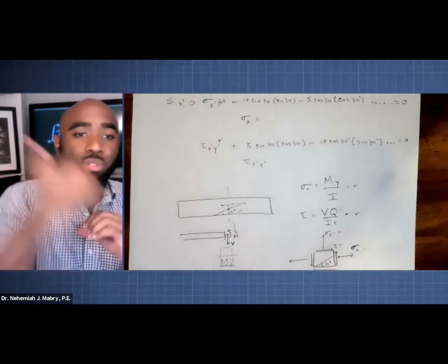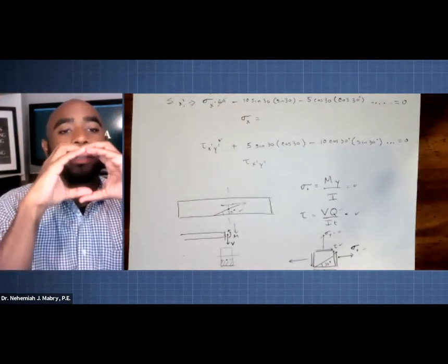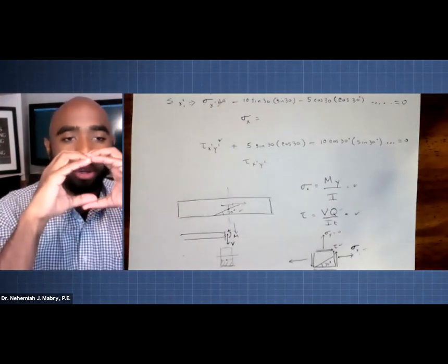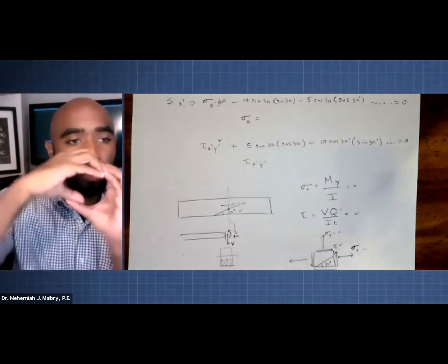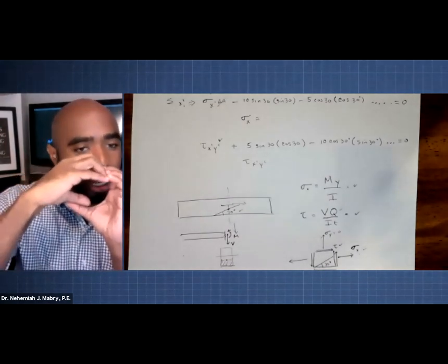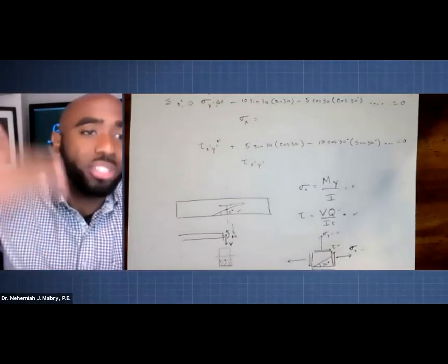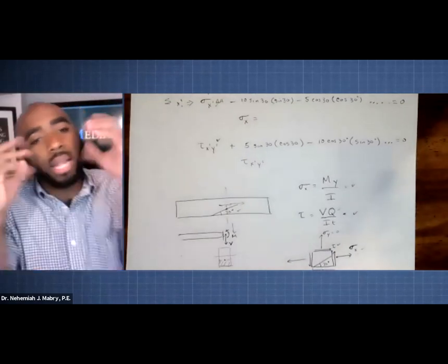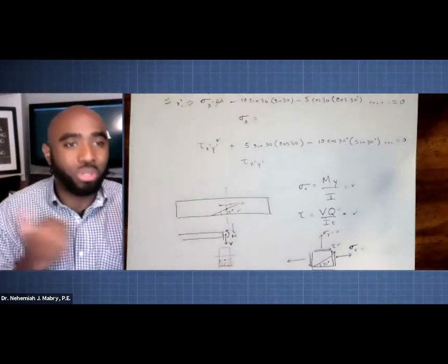Let's just say the maximum stress is in this direction and that direction. Instead of looking at it as just a block or a square that's right side up, you're going to try to find what orientation, what angle, you can make that little piece at, to where now the maximum stresses are perpendicular to its sides. And that's easier to analyze. So it's a matter of finding the angle, and then analyzing it as if they're all normal stresses.